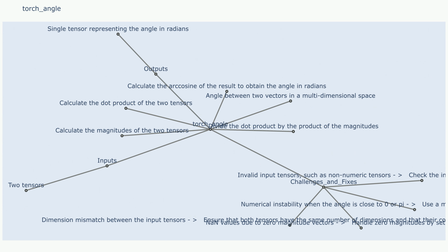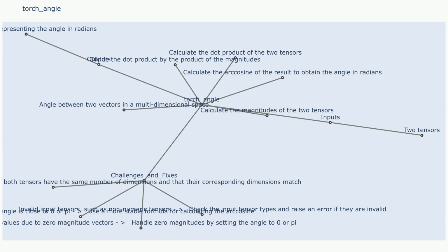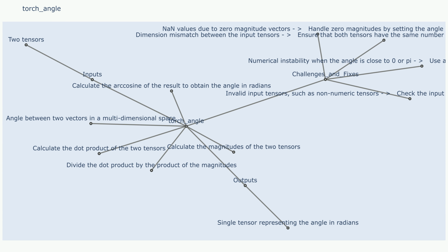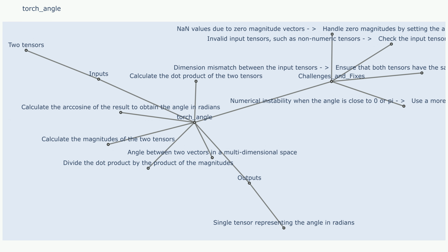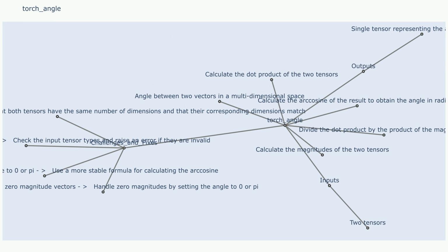Challenges and fixes. Challenge 1: excessive penetration. If the torch angle is too steep, the weld may penetrate too deeply into the base metal, leading to weld defects such as burn-through or excessive undercut. Sample use case that resulted in challenge 1: a welder welding a thin sheet of metal with a steep torch angle, resulting in burn-through. Fixes to challenge 1: reduce the torch angle, lower the torch angle to reduce the heat input and prevent excessive penetration.